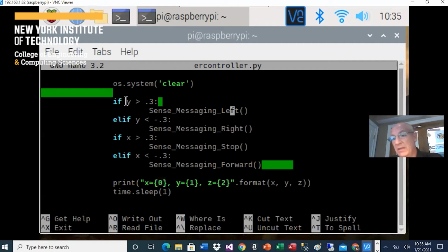So basically what we did, as we were first using the accelerometer, was write a short program to display what the accelerometer was showing. And we got used to the numbers. We figured, when we go left, it's always this. When we go right, it's never greater than this. When we go forward, it's never greater than this.